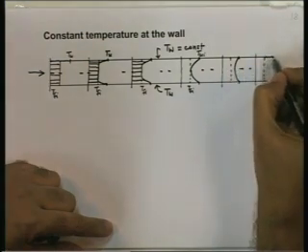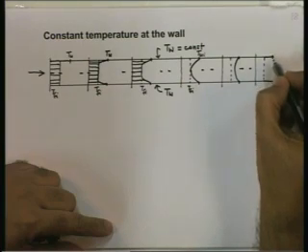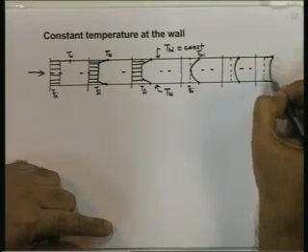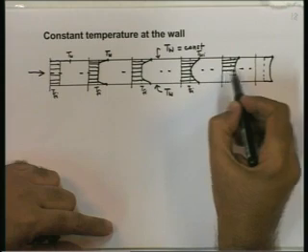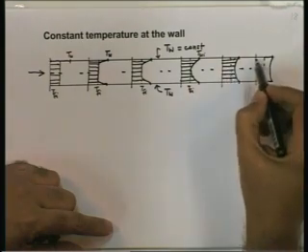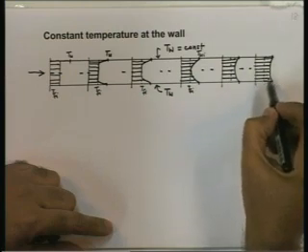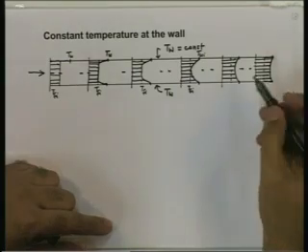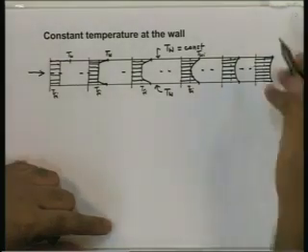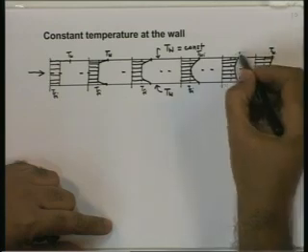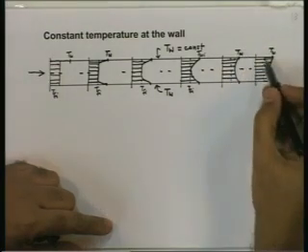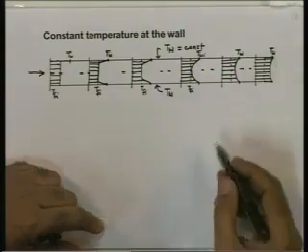And still further down, if this is the wall temperature, it would come much nearer the wall temperature. So the profile, which was initially flat, would go on developing. The flatness in the middle would reduce, wall effect would increase, and then after a long distance, everything would tend to come to Tw. The effect of Tfi would almost be lost.